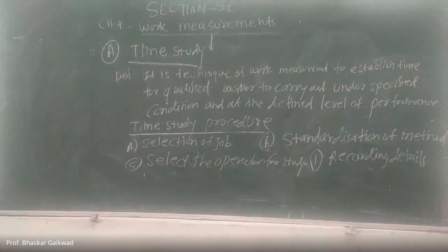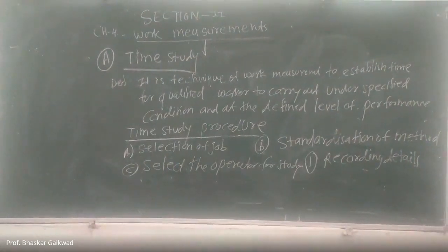The following information should be recorded: identification details like part name, number of machines, speed, materials, operators, and objects. Everything about the materials and workers we have to record. Then the areas of variation, like hardness of material, shape of the job, and other elements which can affect the time for the job.